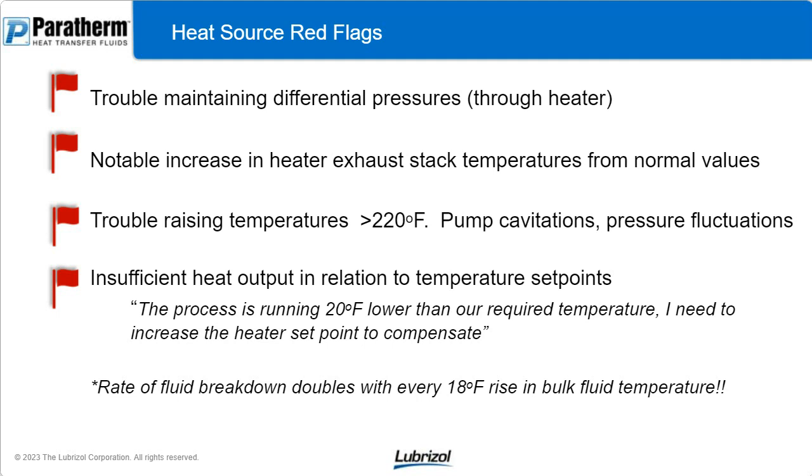Once you expose that to another 20-degree increase, you just doubled the rate of that happening and cut the life of the fluid in half again, and you start to see how these things start compounding. So treat that as a red flag, act on it, talk to your fluid supplier, talk to your equipment supplier, look into it before you just decide to hit a button. All it takes is hitting that button to increase it by 20 degrees to cut the life of the fluid in half, double the rate of degradation, double the amount of maintenance, double the fouling on the equipment, and exponentially you start to have problems that are going to get out of control.